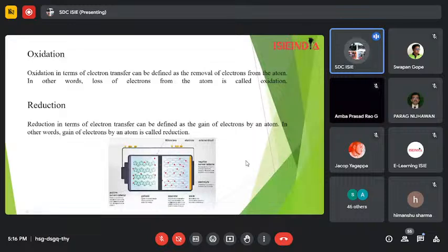Okay, so this is the positive current collector. It will receive the electrons from the external circuit during the discharging of the battery, from the negative current collector, right? You can see the electrons are received by this positive current collector from the negative current collector. This is the cathode. It will store lithium and release lithium ions when the battery is charging. Separator: this will just let the lithium ions pass through. It won't let the electrons pass through.